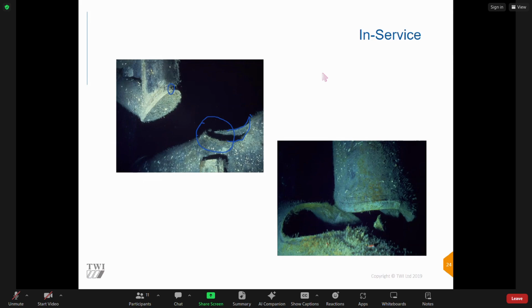Okay, so that bit of steel there was originally, you know, the thickness of the chord there, isn't it? Yeah, so the crack developed, propagated through, and then we've got very rapid failure at the end, and then you can see how far it's moved away. Okay. Same with this one. I think crack initiation point was somewhere around there. Yeah, that thickness of material, same thickness as that. That's the weld. Okay, and then the crack continued around there like that, and then eventually it's failed and that movement away from it.